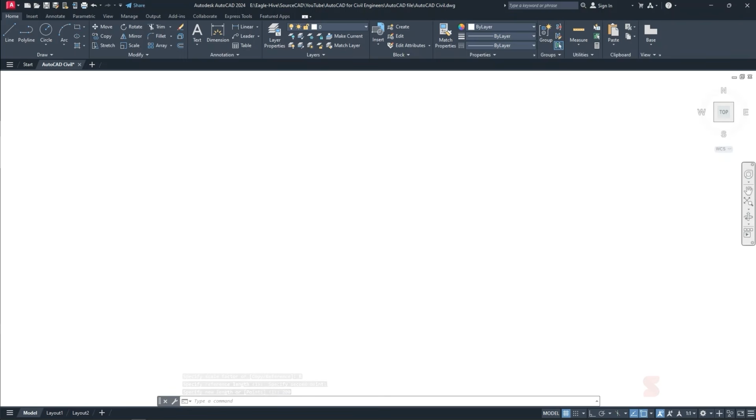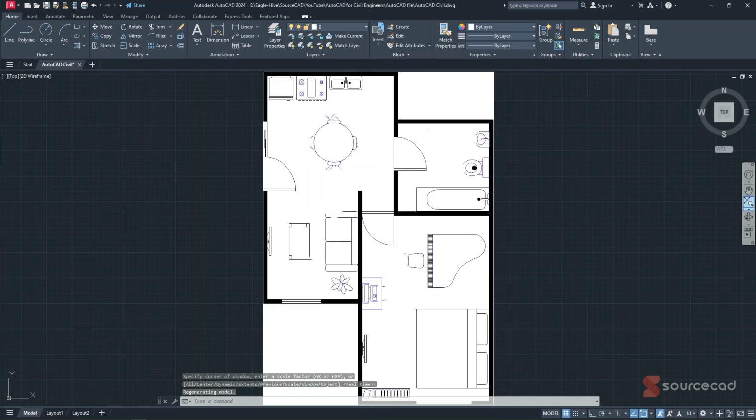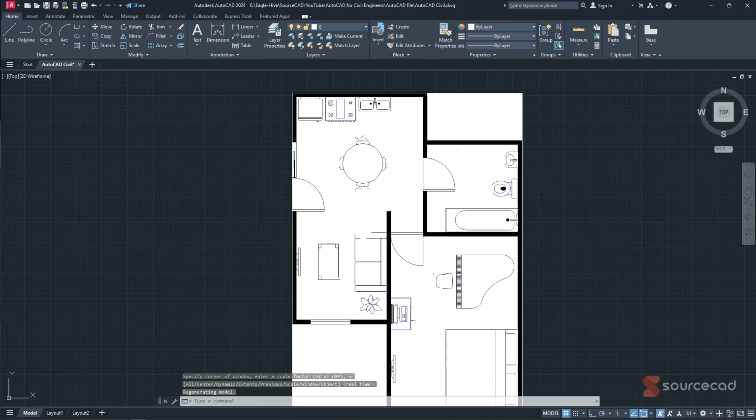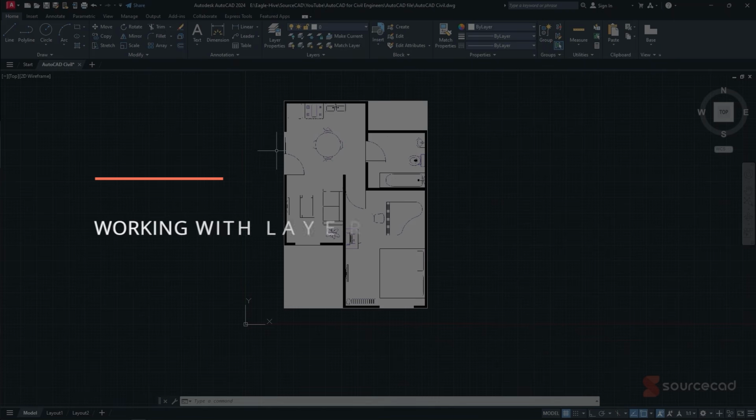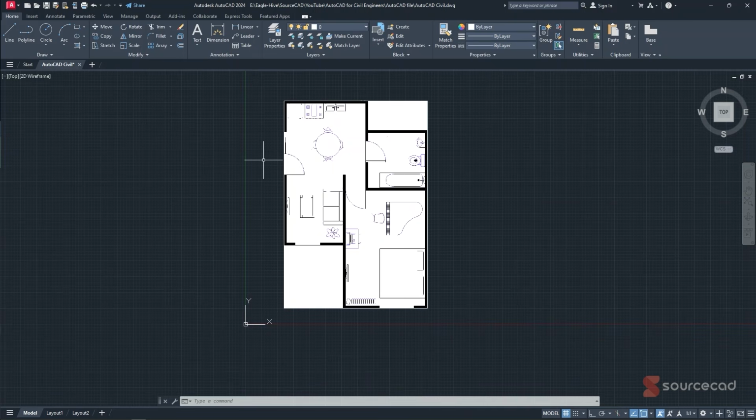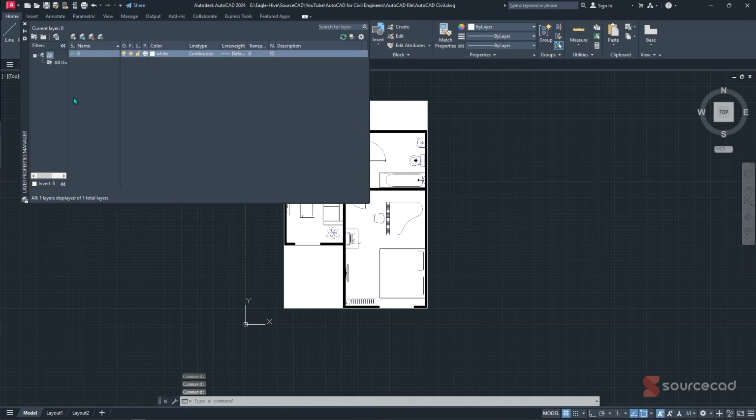So what to do? Just simply click on this option here, which is the zoom extents. And just like that, now we can see our drawing here. So after doing that, we're gonna focus on creating our layers. And the importance of the layers is to help in managing the different items that we have in our drawing. What do I mean? Simply go to the layer properties, click on this once, and this pop-up window will be shown. So we're gonna simply create the layers that we require.